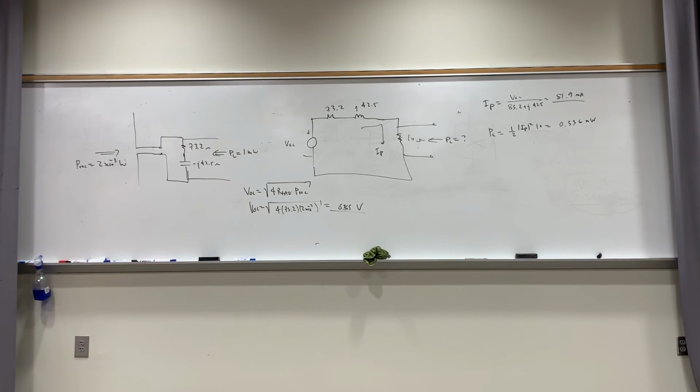All right. What else? You don't have to know the input impedance of the loop antenna. I'm going to assume you know the impedance of an exact half-wave dipole, 73.2 plus j42.5, and for one that's 0.485 lambda, that's only 73.5. Remember, the imaginary part gets knocked off. There's no j42.5 in it. If you just take a half-wave dipole and make it a little bit shorter, 0.485 instead of 0.5 lambda, then it gets rid of that imaginary component.